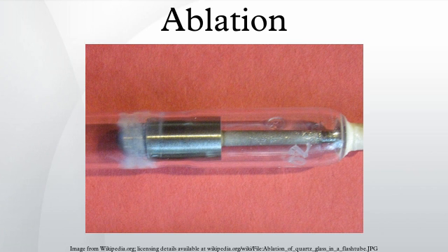In a basic sense, ablative material is designed to slowly burn away in a controlled manner, so that heat can be carried away from the spacecraft by the gases generated by the ablative process while the remaining solid material insulates the craft from superheated gases. There is an entire branch of spaceflight research involving the search for new fireproofing materials to achieve the best ablative performance. This function is critical to protect the spacecraft occupants and payload from otherwise excessive heat loading.